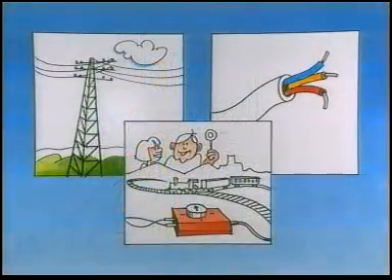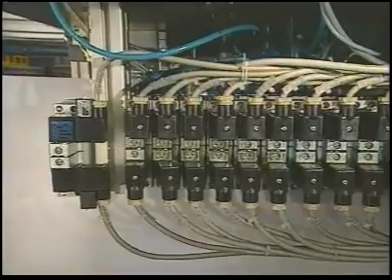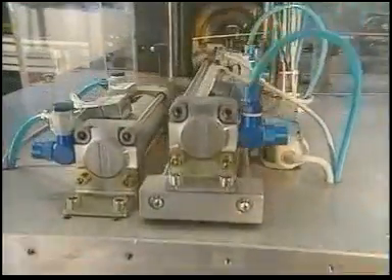Other protective measures. High voltage cables are laid in such a way that no contact with them is possible, or so that no voltage can jump across. And current carrying lines are insulated. And finally, low voltages are used wherever possible.